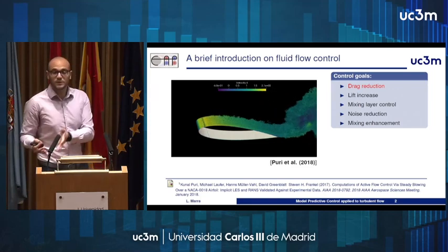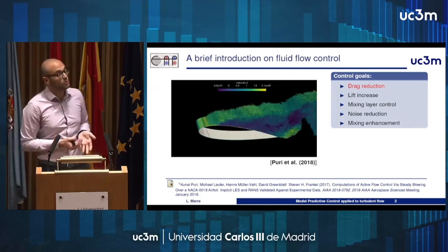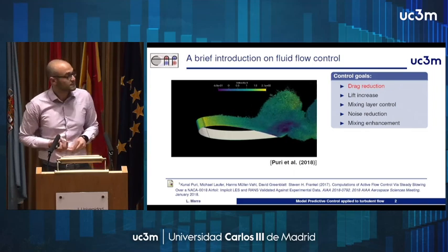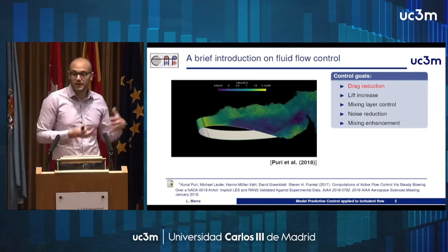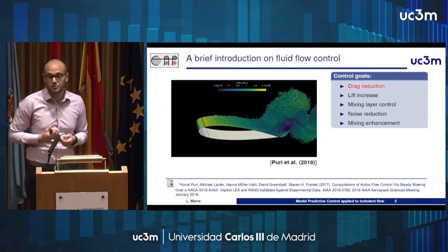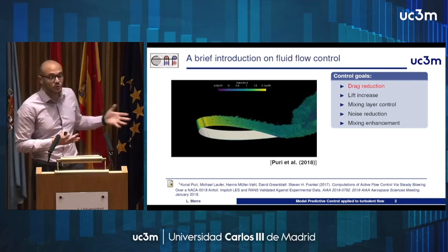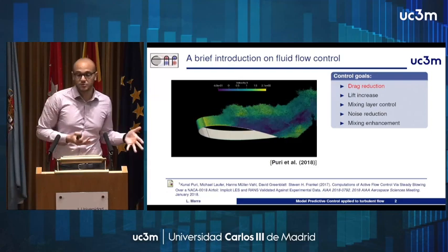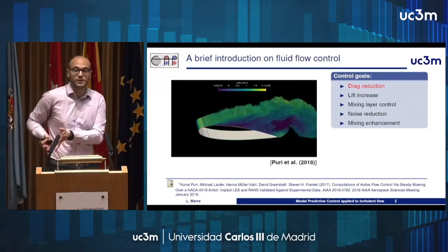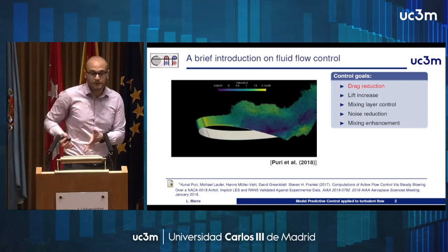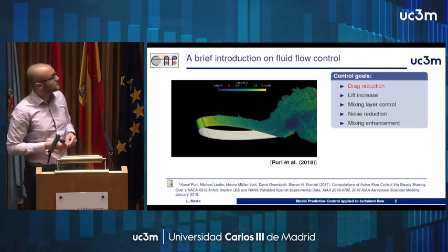When moving to 130 kilometers per hour, it accounts for 80% of the total resistance. Some results have proved to be effective, because we can reach a 25% drag reduction. That also means producing less CO2, specifically 2 kilos every 100 kilometers.